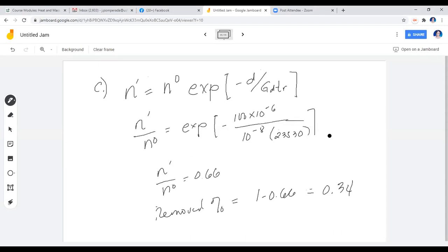So this formula accounts for what is inside the crystallizer. The one that you're not able to account is the one that was removed already. So that is in letter C, based on the original question of the percent of nuclei removed in the discharge by the time they have grown to 100 micrometers. They were removed already because they have reached the size requirement.